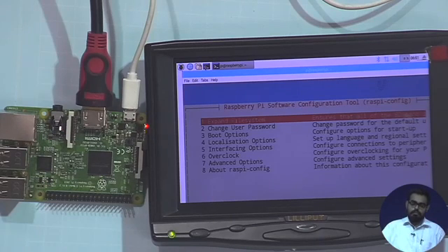But post first time installation of your Raspberry Pi, you need to expand your file system because these images are more or less compressed, and if you expand the file system, it will cover your entire memory card. Suppose I'm using a 32 GB memory card, but the image was approximately 2 GB. So it will now expand to cover the maximum of the memory card. So you'll have lots of space for additional functions, installing new software, putting on files, etc. Once you expand the file system, after this operation is done, you reboot the system.